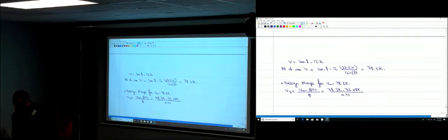So that's 78.3 K minus phi Vc, which is 32.018 K, divided by phi, which is 0.75. So Vs is 61.709 K. Okay?